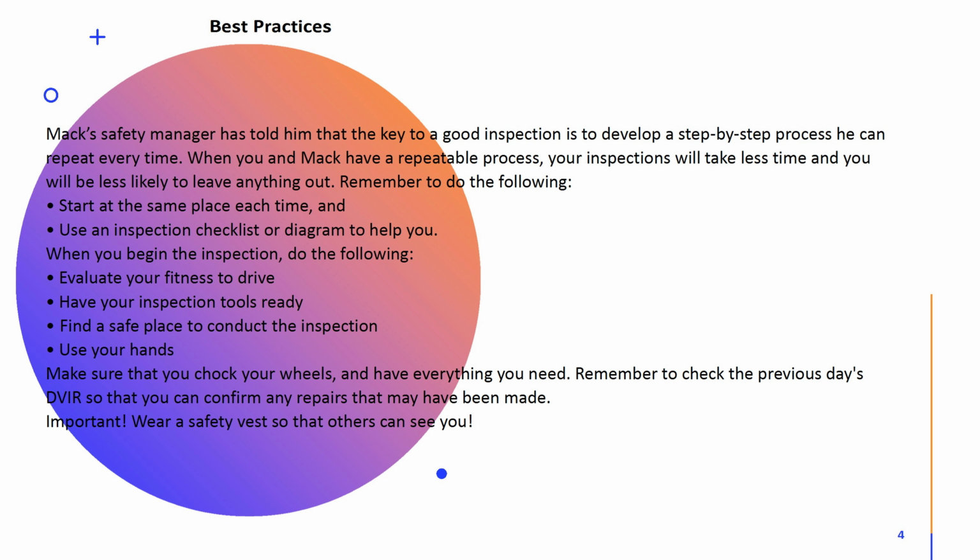Remember to do the following. Start at the same place each time and use an inspection checklist or diagram to help you. When you begin the inspection, do the following. Evaluate your fitness to drive. Have your inspection tools ready. Find a safe place to conduct the inspection.